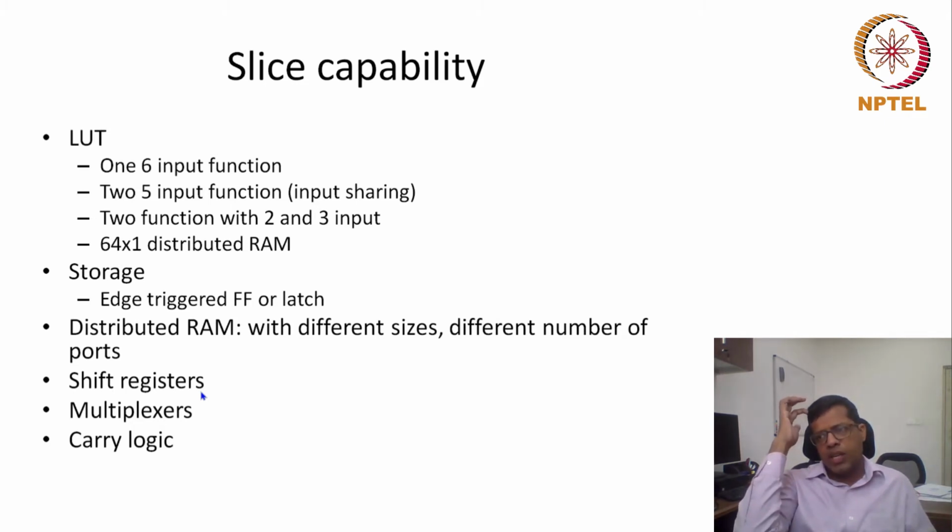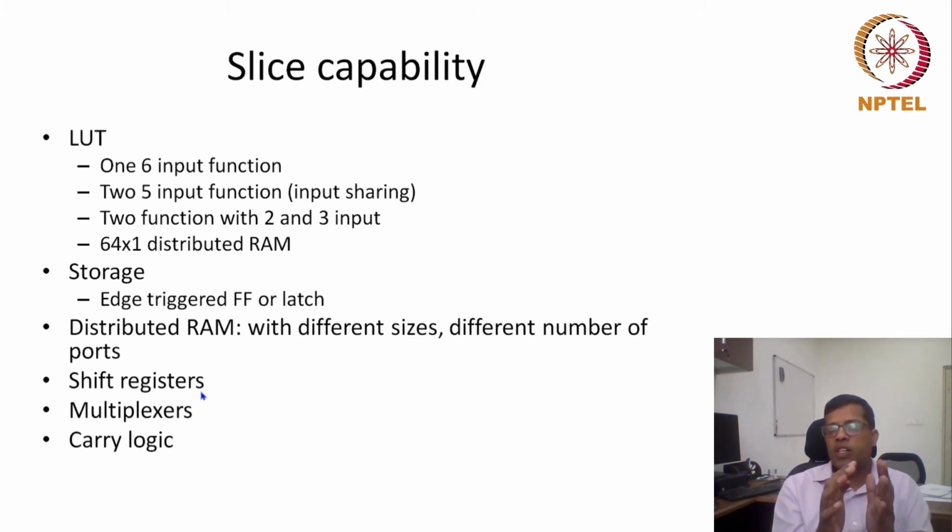So these slices can also effectively work like a multiplexer, and as I said earlier, there's a carry chain, so they can effectively work like an adder or ripple carry adder. Okay, so now you see within the slice or within a configurable logic block there are a good amount of hard connections as well as programmable connections. So the same logic block can work like different logic based on the requirement.